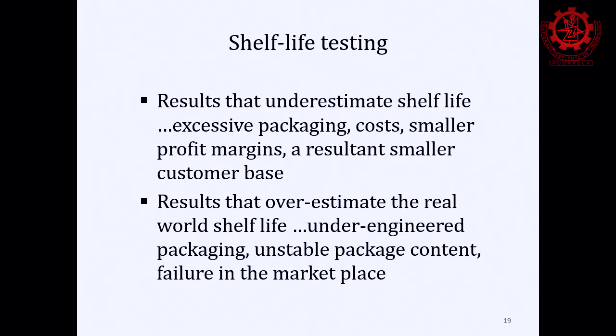So for shelf life testing, it is important both ways that you don't want to underestimate the shelf life, because if you underestimate, then you are going to select very excessive packaging, and excessive packaging is going to cost money, right? But if you overestimate the shelf life through your shelf life testing, then you are going to under-engineer your packaging, and then your product may fail. So you really want to have the optimal packaging.